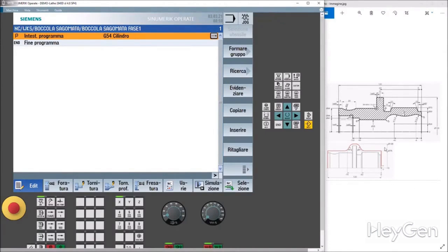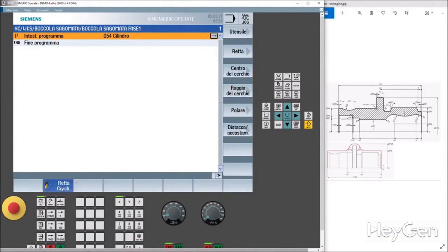a piece arrives that is poorly stamped or has some protrusions, we can say that they might cause problems in the following machining. A chamfer will ensure that all the machining has a fixed starting point, which will be the Z0 of the first chamfer. It could also be Z01. Let's go with the little arrow from this menu, in, a straight circle.